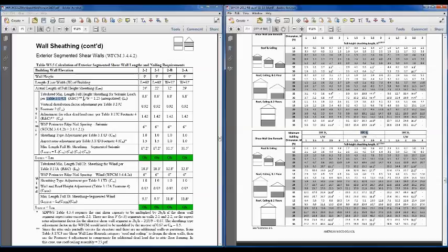Our length to width ratio is 1.25 in the workbook. So again, we end up having to interpolate here in the tables between 1 and 1.5, but with that roof and ceiling, we come down here to a building dimension of 40 feet, let's see, length or width minimum, W. So we're looking at W, which is 32 feet here.